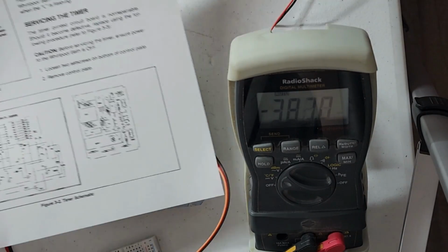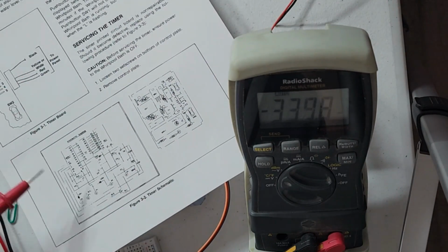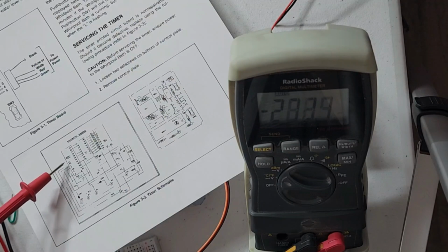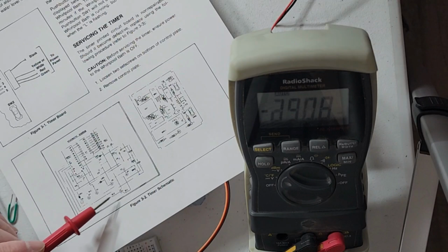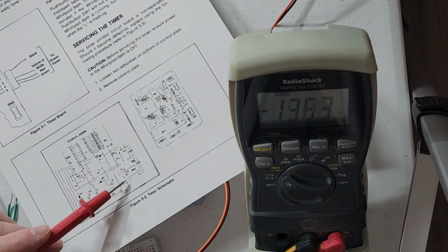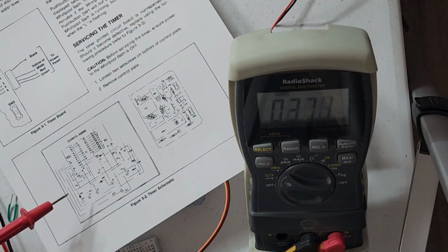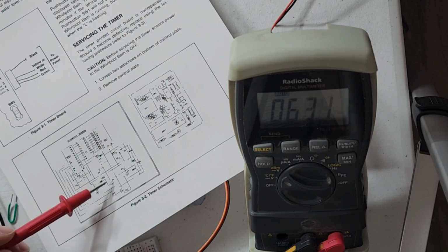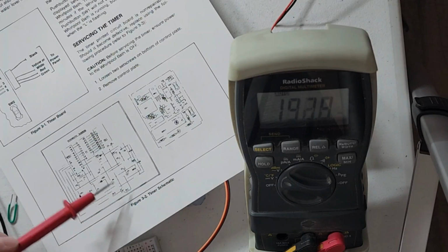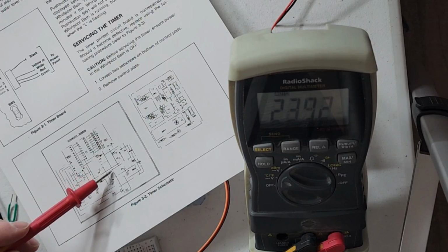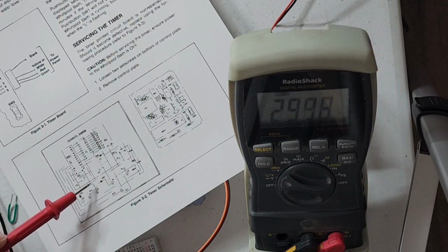Let's see if we can see on this schematic. That transistor is right here. It's so hard to see where things go. That is pin 21, it looks like. It turns this transistor on for pin 4. That's number 4. 1, 2, 3, 4, 5. Pin 2 is connected to nothing. Pin 3, pin 4 turns the motor on. Okay, so that turns the motor on. So this transistor turns the motor on, right? Yep. That would go to pin 4 to turn the motor on.